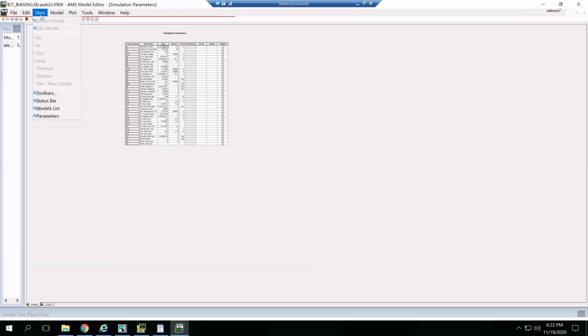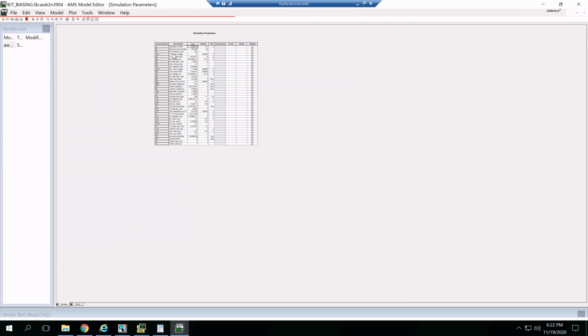Let's see if I can make the view a little bit better. This is horrible. I'm not sure why it's scaling it so much on mine. Apologize for that. So hopefully you can see it. It's the second line is the BF value, okay? This is your maximum forward beta. The value is currently at 254.395, and the default value is 100.